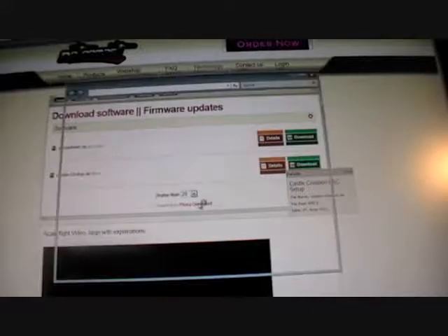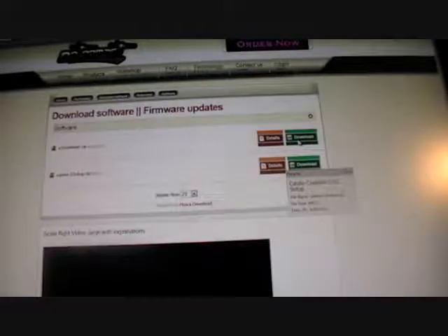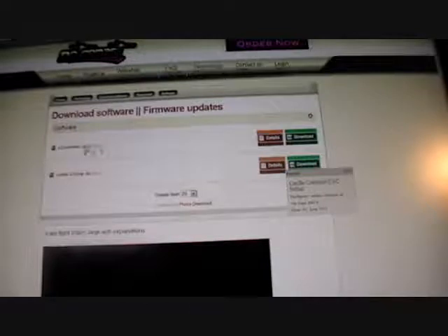This makes it a lot easier to set up the Castle Creation speed control. You can just dump this in as long as you have the data link for the Castle speed control also. So just dump those in a folder. It's important that all the controller software be in the same folder. It needs access to each piece of the software to actually operate.